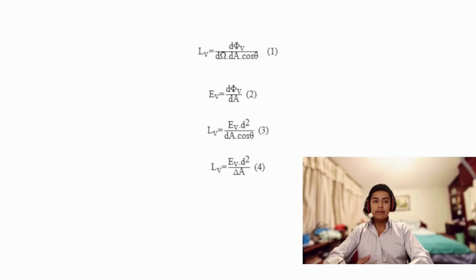In this way, the most commonly used procedures for luminance calibration focus on direct comparison, which involves contrasting a reference device against a luminance meter under calibration. In this process, a luminous surface is measured, which could be the aperture of an integrating sphere. The difference in readings between the equipment under calibration and the reference equipment is then used to determine its error or correction. This research established the influence on calibration uncertainty introduced by the lack of complete uniformity of a surface.